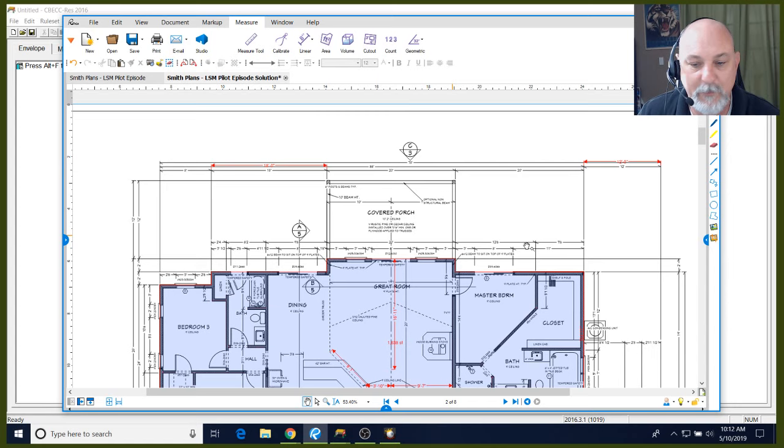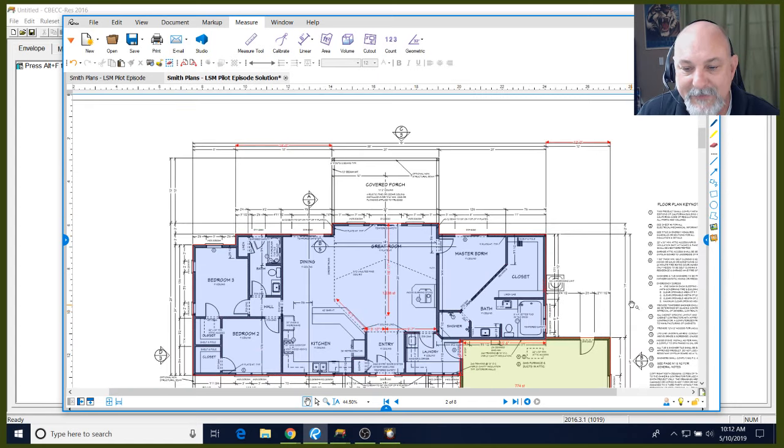We just need to collect the information for the right wall, and that's our dimensions 19 feet plus the additional 2 feet. So 21 feet times 9 gives us 189 square feet. So good, we've got our house, our conditioned space, wall takeoffs done.